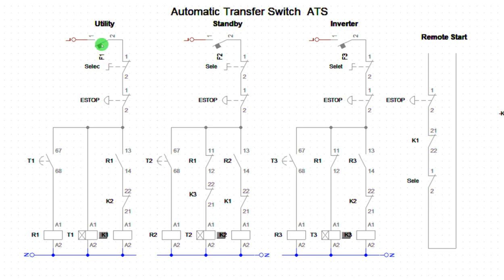Let's try that now. Main is active, is counting. It has entered. Look at it, here open. The genset will shut down. That is the second means. The third one is by putting this on manual. Putting the genset on manual. You don't want it to start when mains fail. You activate here. Look at it. Here is open. So when you do that, genset cannot start because here is open.